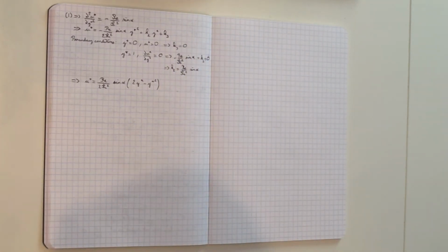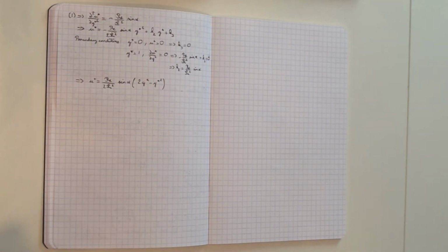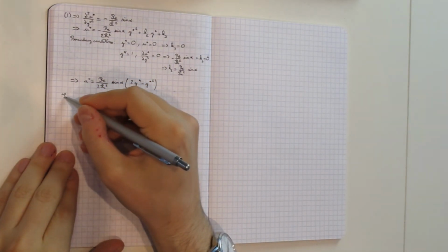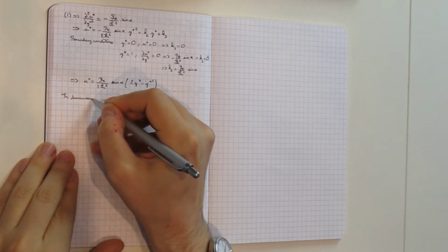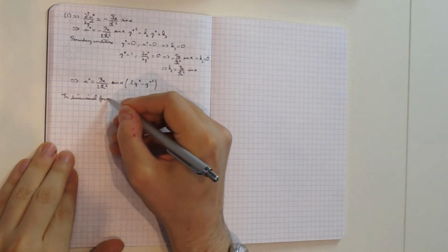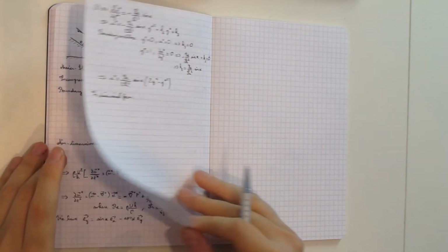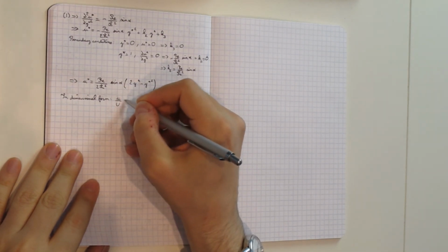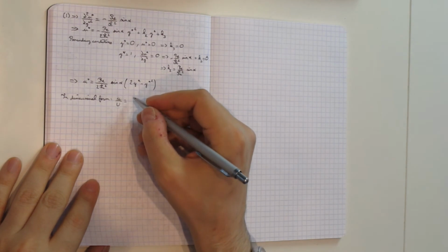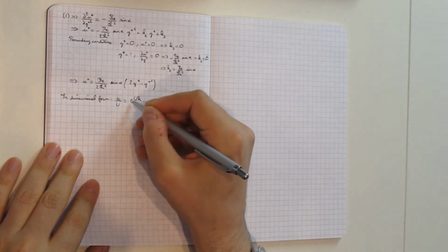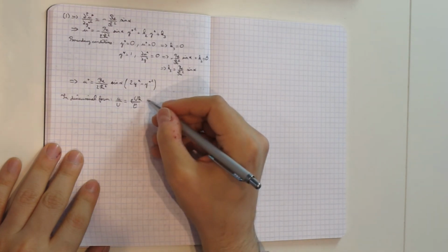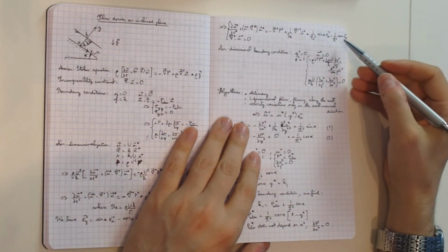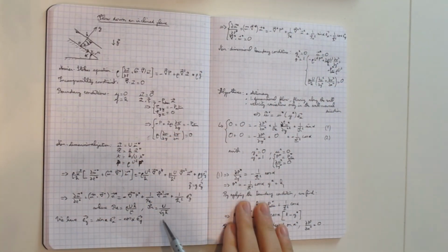Okay, so one last thing that we can do is to turn this into a dimensional solution. So we can write this in dimensional form. U star has to be u over capital U, so that's our dimensional u divided by capital U. Then I've got my Reynolds number, which is rho UH over mu, divided by 2 if I want, times 1 over the Froude number squared, which I defined here.